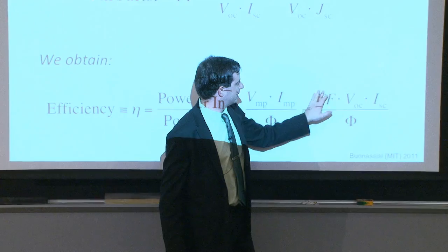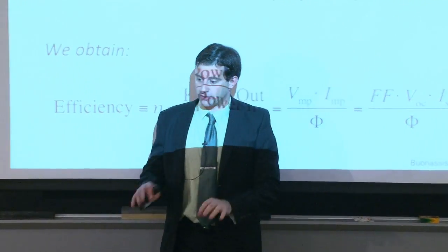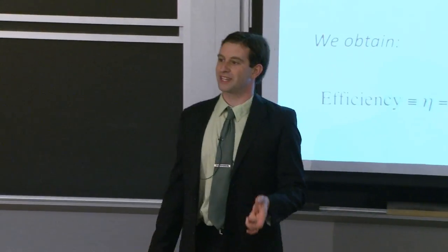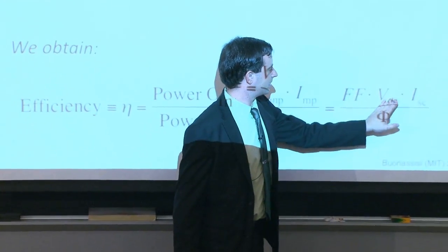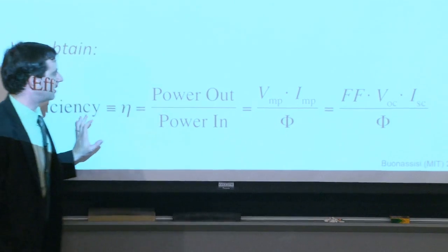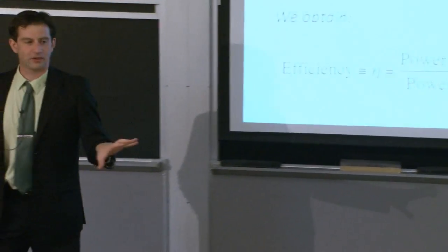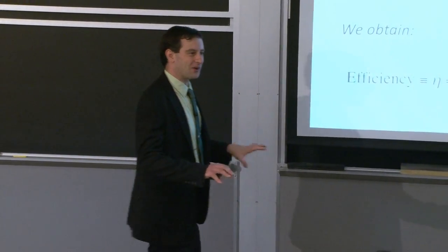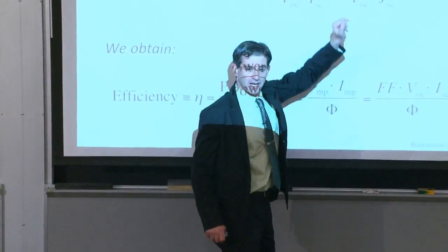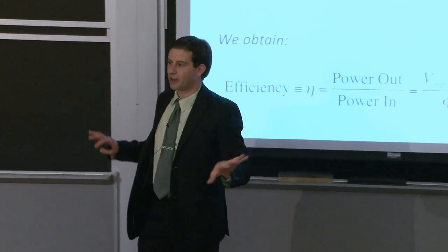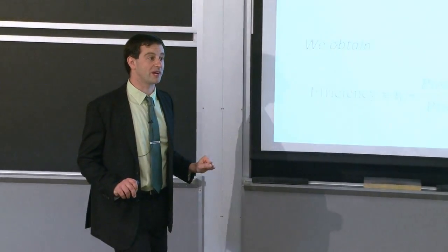And the fill factor is going to be a function of the interface diode characteristics, but also of the resistances within the device. And so from an engineering point of view, we break the solar cell output down into these three parameters so that we can better understand what's going wrong with our solar cell. If we have everything lumped in terms of Vmp, Imp, it becomes a little bit more obscure to figure out what exactly is going wrong with our solar cell device.